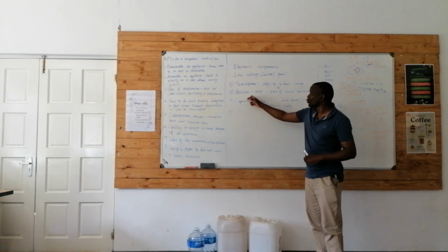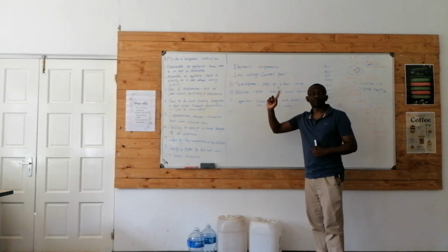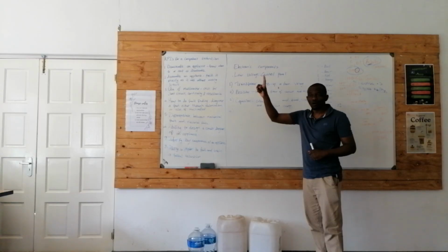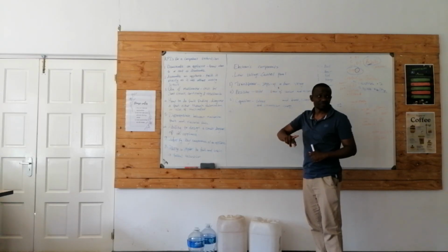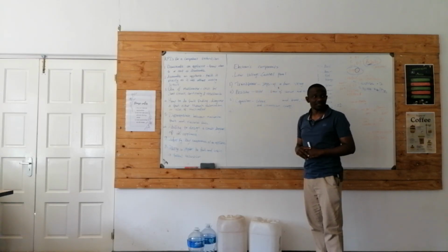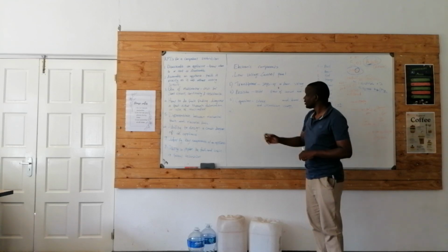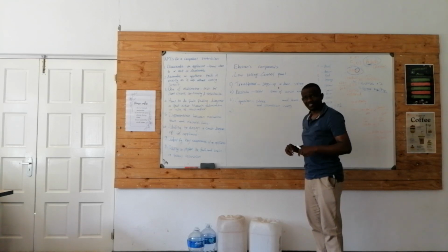If you don't know the resistance, always start from the highest, mega ohms, and go down. Does that make sense?